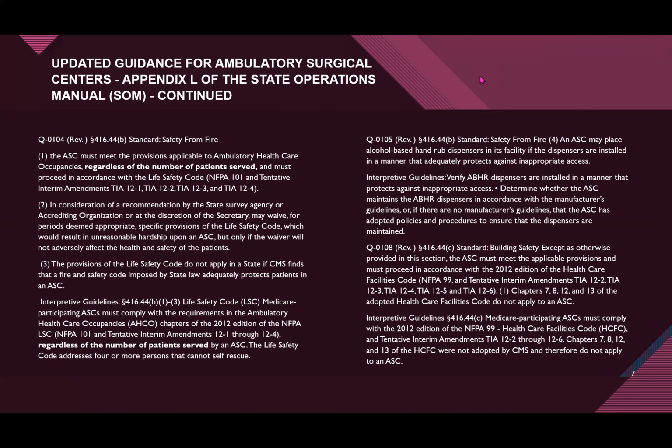It talks about alcohol hand sanitizers may be placed in dispensers throughout the facility, and this is a fire issue. And so before COVID, they were very picky about where alcohol-based dispensers could be installed in clinics, in ambulatory surgery centers. And what they have done is they've loosened that regulation, and there's an amendment in the life safety code that says we can have alcohol-based hand rubs around. And so if you have any area that's carpeted, you have to be sure that you are sprinklered.